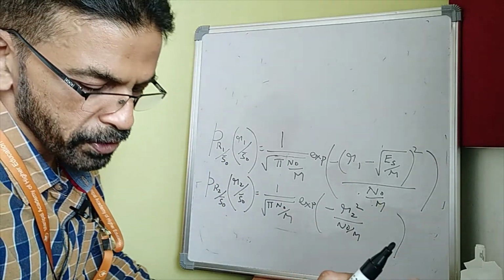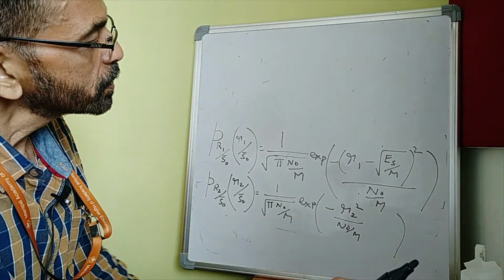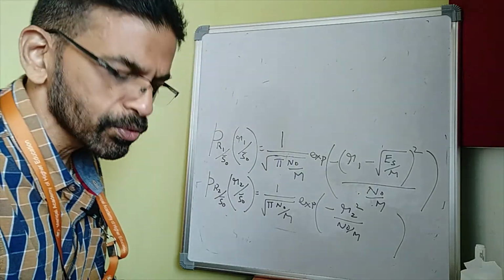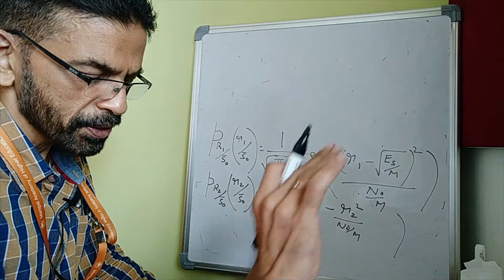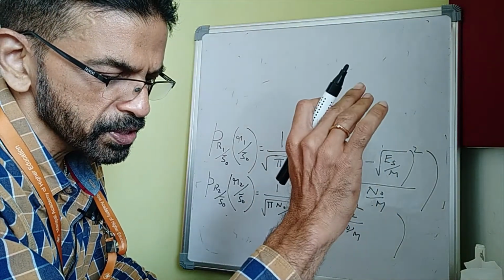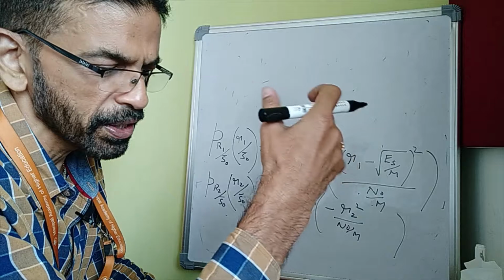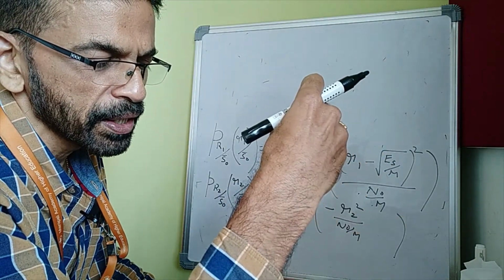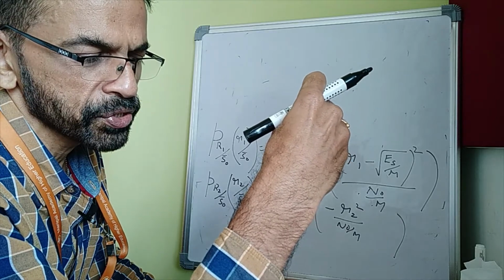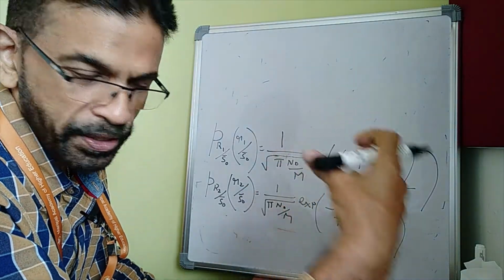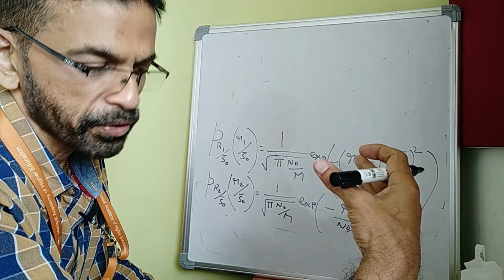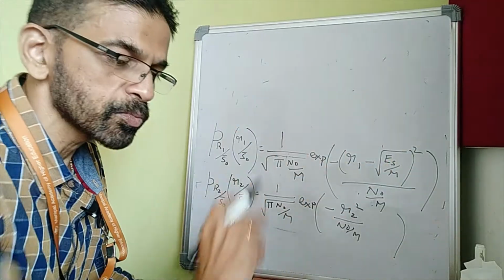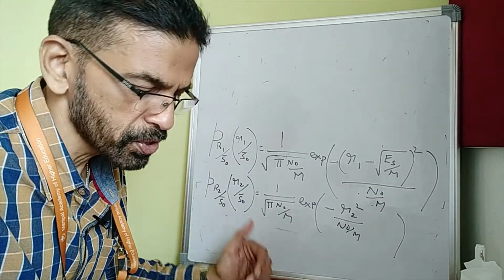So let us first find out, since we have assumed that S0 T is the transmitted signal, the probability that S0 T is detected correctly. And remember from the discussion in the previous video, a decision is taken. We had broken down the entire decision making process, and we arrived at the conclusion that a decision is taken by the receiver by determining which of these R's, that is R1, R2, R3 up to Rm, is the largest, and then the corresponding signal was transmitted. This is how the decision is taken.